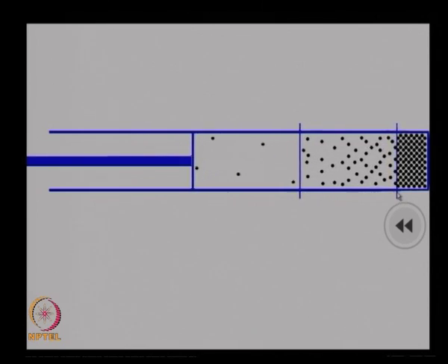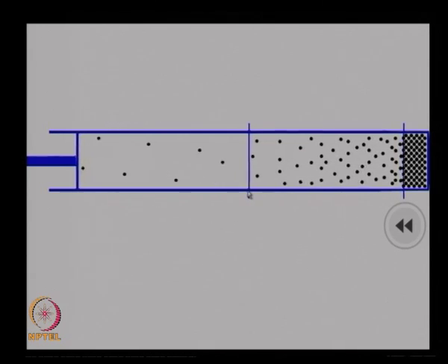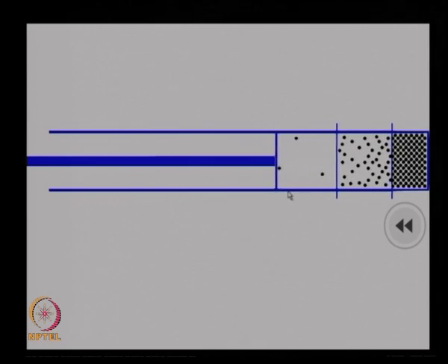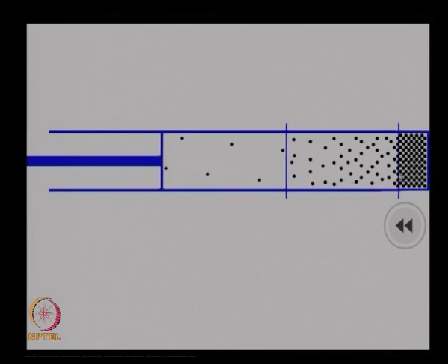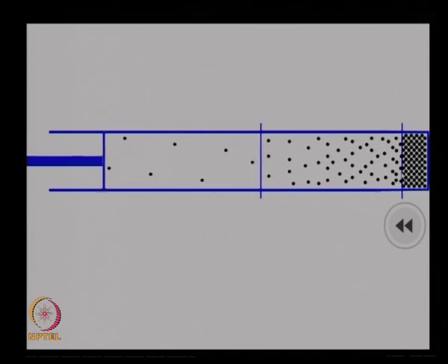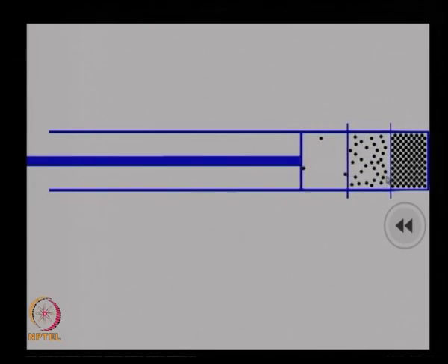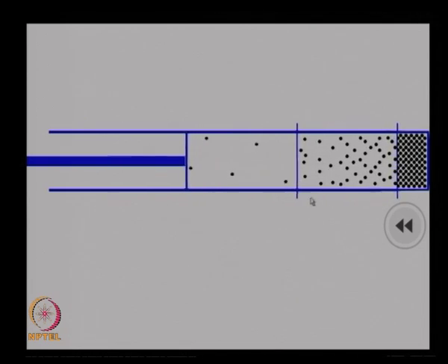This is the first expansion wave, while this is the final expansion wave, which tells that after that the velocity is constant, nothing more changing there. And this is your high pressure gas which is slowly expanding because this wave is going and telling there is lesser pressure here. In fact, I have drawn only 2 lines here. Ideally I should draw an infinite number of lines. Yes, there are so many waves here.